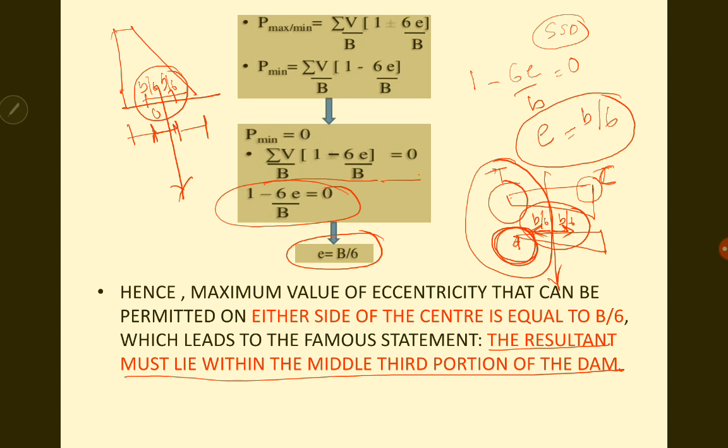If the dam is empty, the reverse happens. The resultant will be towards the heel. The heel will be in compression and the toe will be in tension. When the compression goes on increasing, the tension at the toe will also increase, and if it exceeds the permissible limit, a crack will be formed at the toe. This crack reduces the effective area of the structure and increases the stresses, leading to more and more cracks, and finally the structure will fail. This is the case of tension cracks.